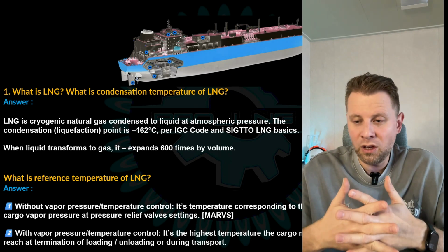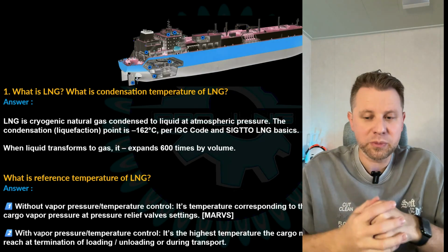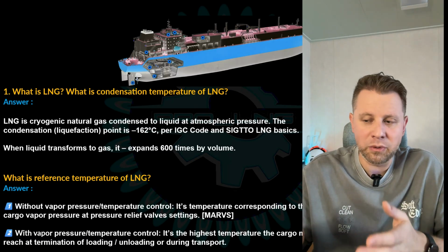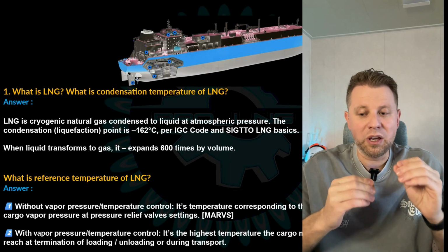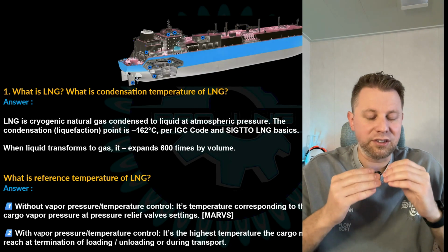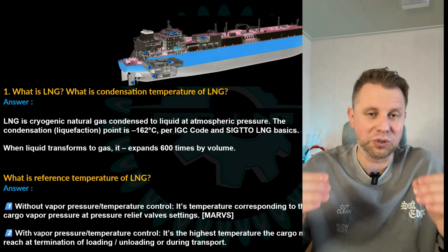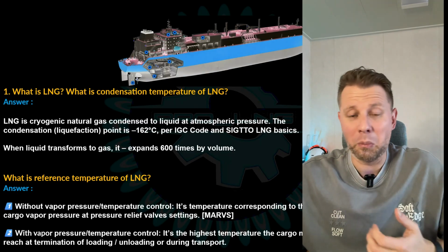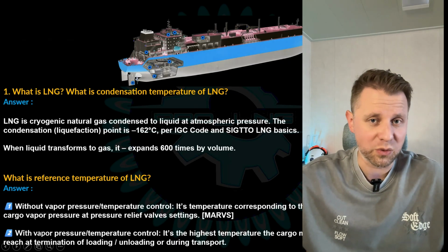So basics: without vapor pressure and temperature control, it's one condition. The temperature corresponding to the cargo vapor pressure at pressure relief valve settings, maximum allowable relief valve settings, MARVs. And the second definition, with vapor pressure and temperature control, is the highest temperature the cargo may reach at termination of loading or unloading operations or during transportation. So this is what he wanted to hear. Just remember it. There is little chance you will be asked, but eventually, someday, a SIRE inspector may approach you with this question.